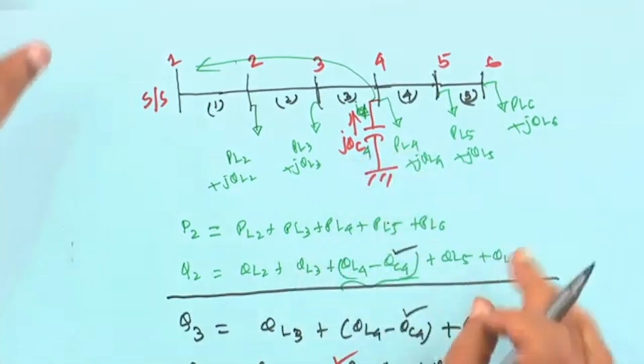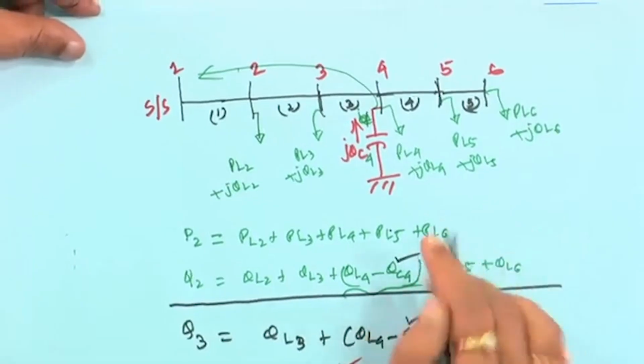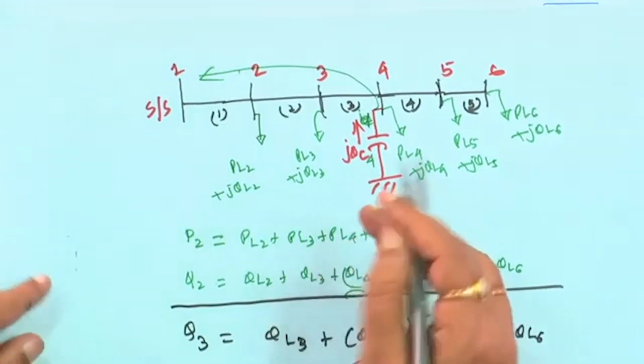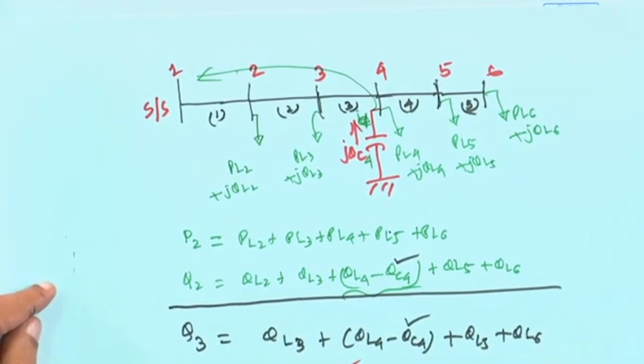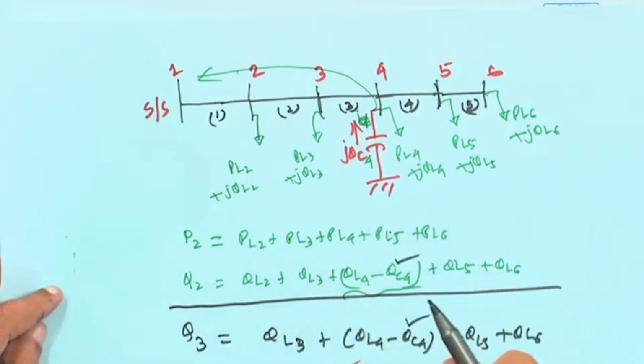That means branch losses will reduce due to capacitor placement whenever you use a shunt capacitor. For the series capacitor, we will come to that in the capacitor application. The main purpose of a series capacitor is to increase the voltage magnitude at each node. As the voltage increases, power loss, which is inversely proportional to the square of the voltage magnitude, also decreases.